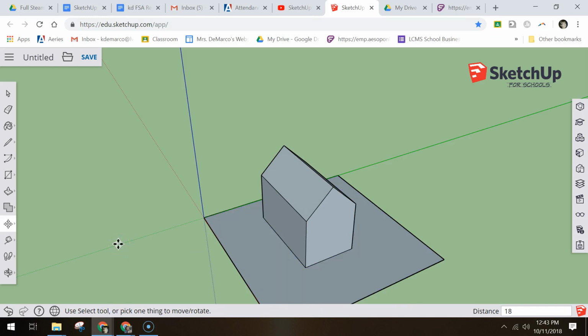Next, we're going to actually create the roof by using the push-pull tool again. We're going to click on push-pull, and now we're going to hit Control on the keyboard. We're going to hit Control. You should see a little plus sign next to the icon of the push-pull now, which is going to mean we're going to copy and make an additional layer onto the roof. So we're going to click one time, drag it out. Doesn't matter if you drag it way out or a little bit out, but make sure it doesn't go in. We definitely want it to kind of come upward. And we're going to type 4 enter, again implying we want 4 inches.